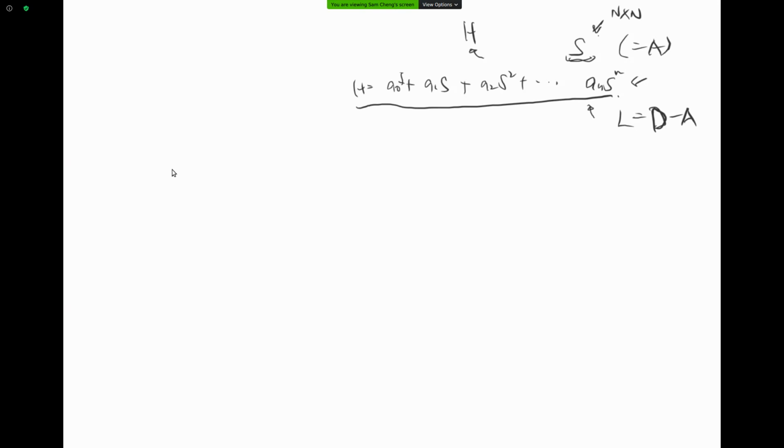If I have discrete time and a shift operator, maybe it's just the Z operator, then this is a representation of the filter in terms of the Z transform of the filter. For example, a filter can be written as A0, and of course typically I will have A1 Z inverse instead, because I cannot have a long non-causal filter, so it has to be a delay.